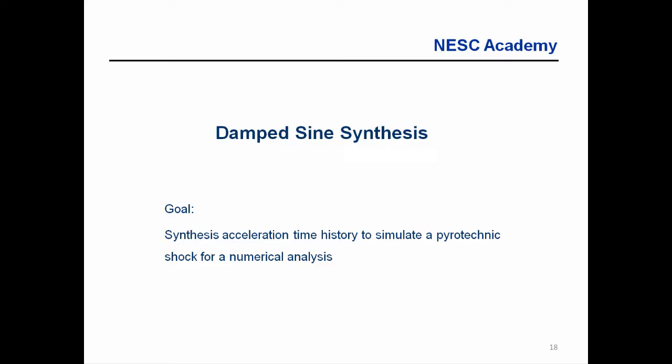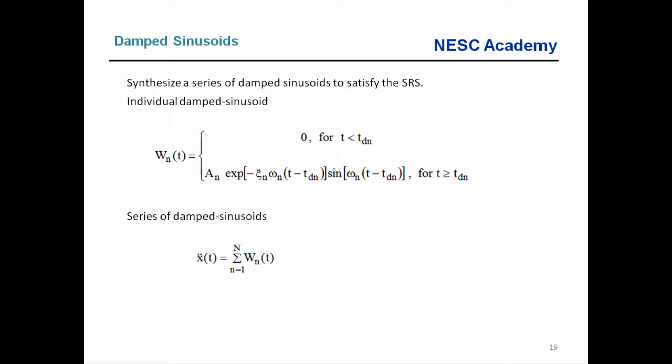So the specification that we actually take into the test lab is much more conservative than the SRS from our actual measurement. But anyways, the goal here is to come up with a plausible time history that matches that SRS, and then that time history could be used, say, for a base input for a modal transient finite element analysis. So we're going to synthesize a series of damped sinusoids to satisfy the SRS. It's almost a tongue twister there.